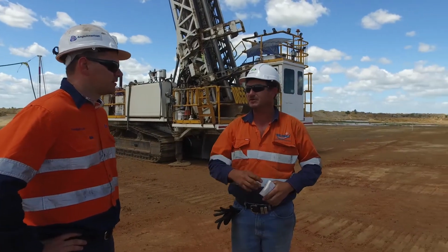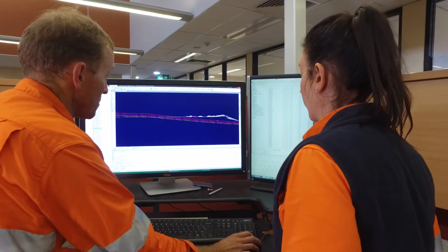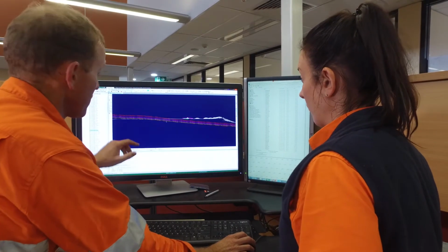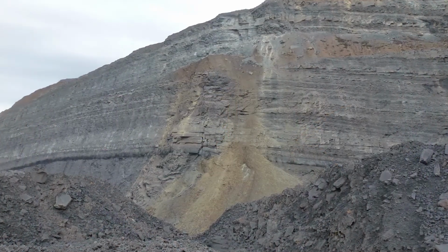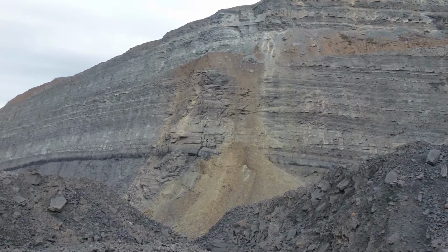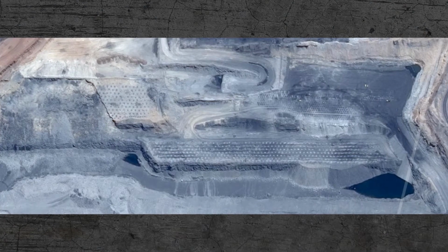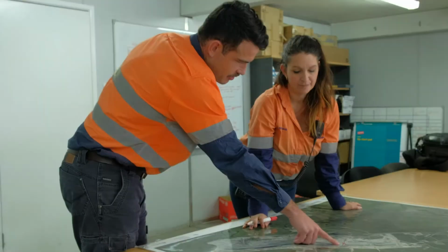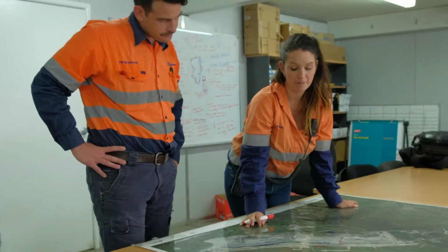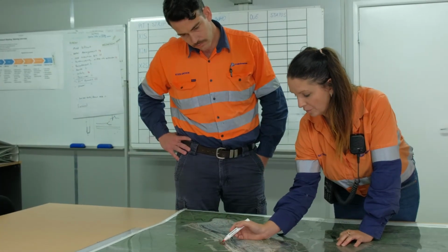With this information, mining engineers, drill and blast engineers, and geotechnical engineers work together to produce the optimum design geometry for mine safety and productivity. For example, geotechnical engineers want to avoid sharp 90-degree elbows or bull noses as much as possible in the mine design to minimise blast damage and exposure to adverse structure. If such geometries are observed in the mine plan, the geotech may make recommendations to modify slope geometry to improve stability.